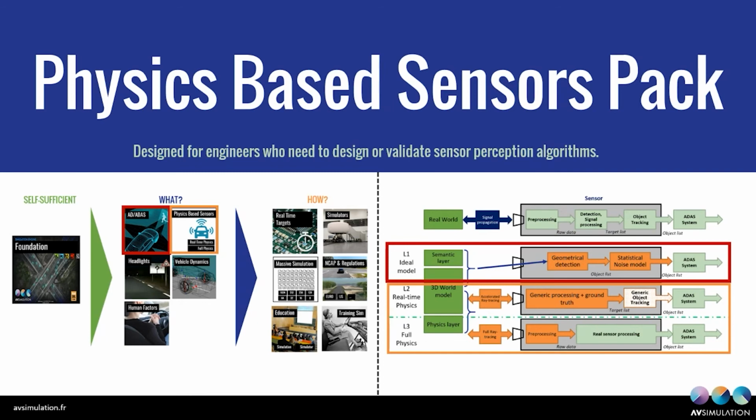So if we do the exact same simulation that we have seen with the default scenario, if we use LiDAR instead, and if we go to the control pad module to see the different messages, you will have access to the output of this LiDAR in the SCANeR Studio simulation bus. And then, as always, you can have access to this information through our different API to, for example, feed your ADAS system with this output of LiDAR at level 2.